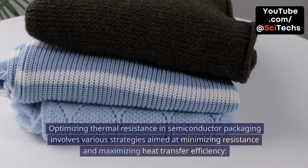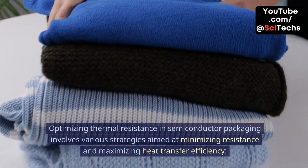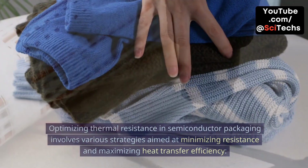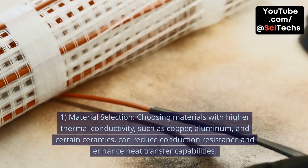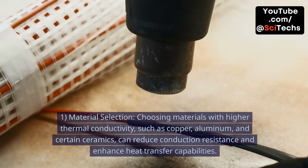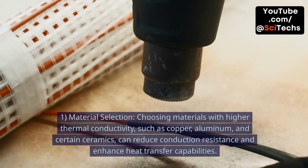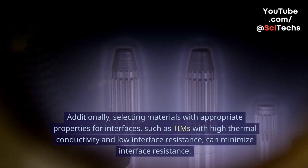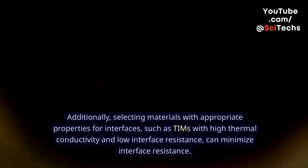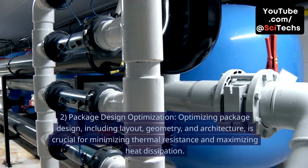Optimizing thermal resistance in semiconductor packaging involves various strategies aimed at minimizing resistance and maximizing heat transfer efficiency. 1. Material selection. Choosing materials with higher thermal conductivity, such as copper, aluminum, and certain ceramics, can reduce conduction resistance and enhance heat transfer capabilities. Additionally, selecting materials with appropriate properties for interfaces, such as TIMs with high thermal conductivity and low interface resistance, can minimize interface resistance.